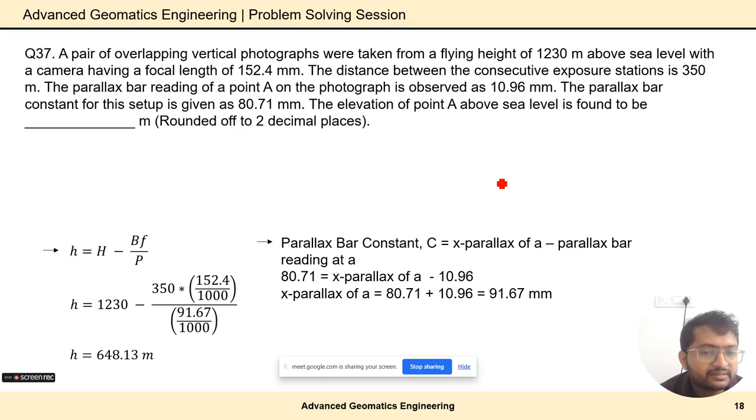We'll take a reading at A, which will be the full reading, and then we will measure what is happening in the parallax bar, so that we will either deduct or add depending on the error with reference to some benchmark point which we have already made here. Got it? If not, I will describe it with some figures in your annotated file, so you can look into that as well.